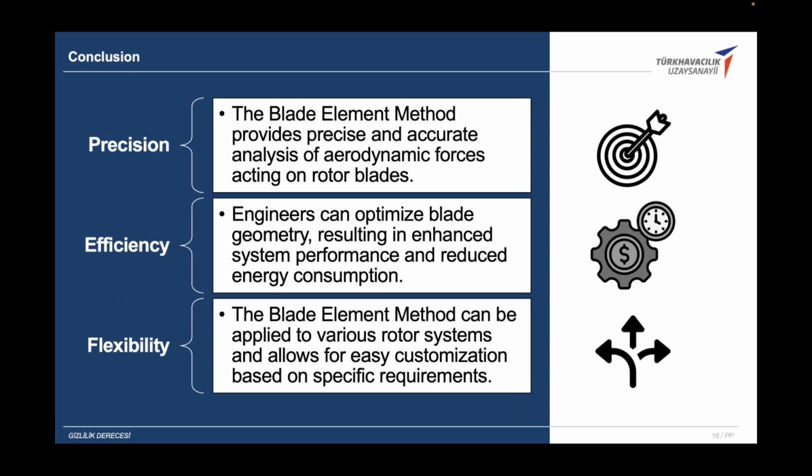Also, you have to run your rotor bodies with a rotating domain in other CFD methods, and it has to be an unsteady case, but with this actuator disk method, you can run your analysis in steady conditions. It's also flexible. Users can customize their cases by only changing the rotor model input file.